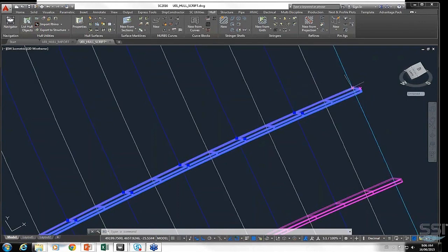And then the pink is just telling you what the endpoints are of those stringers. So by selecting these, we could actually do some funky stuff by modifying them. And we will modify one in a moment, but you can see that obviously I can't select a point here where that visible is. And so that's one of the major differences between setting some points as control sections and some as visible.